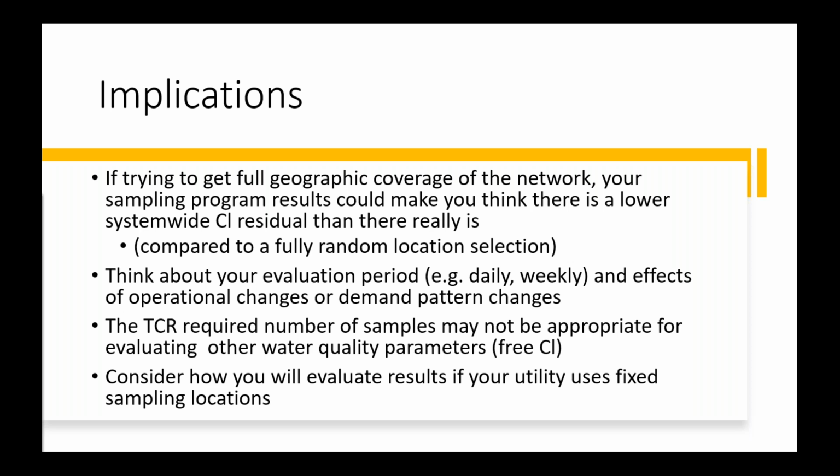We also see that the total coliform rule required number of samples might be fine for total coliform, but for other water quality parameters such as free chlorine, maybe a different number of samples might be more appropriate. And then it's really important to consider how you're going to evaluate your results if you use fixed sampling locations in your network.